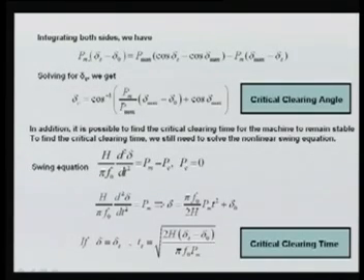on the left hand side, you will have PM times (delta C minus delta naught). On the other side, it is Pmax (cos delta C minus cos delta max) minus PM (delta max minus delta C). Here the delta C terms cancel, and we get one equation of delta C very easily. So delta C will be cosine inverse of PM upon Pmax times (delta max minus delta naught) plus cos delta max. And delta max can be determined again.